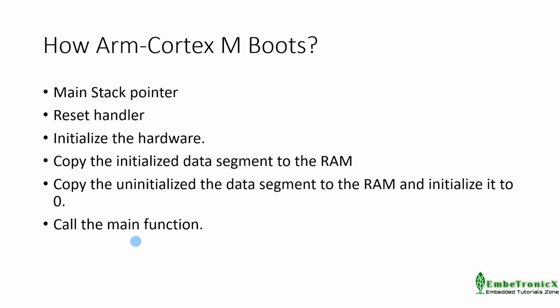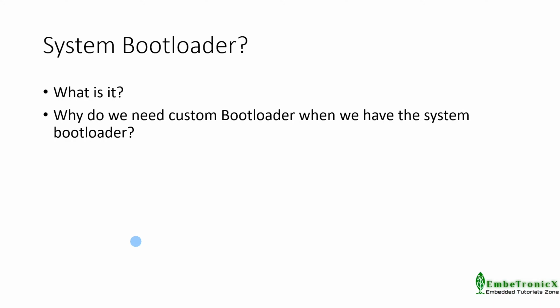Is there any bootloader available already in the microcontroller? Yes, there is. Each latest microcontroller has a system bootloader that is provided by the chip manufacturer. It will be stored in the ROM section. The microcontroller has boot pins. Using that, we can run this system bootloader. Why do we need a custom bootloader when we have a system bootloader? Using this system bootloader, we cannot do whatever we wish to.